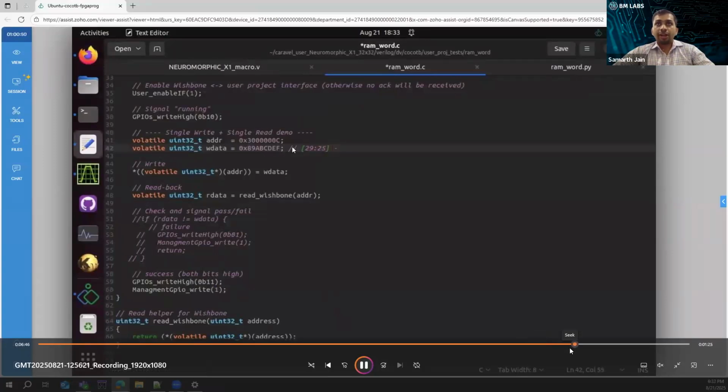So this is the register format in the IP you need to send. If you want to specify the row address, it'll be on the 29 to 25 bit in the crossbar. The crossbar is just like a chessboard, right? So it has XY coordinates, the row versus column. And the column address similarly will be between 24 to 20. And then the EF was the data we want to program into the neuron, which is essentially a ReRAM, which is mimicking a neuron over here.